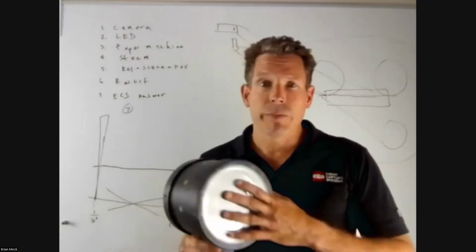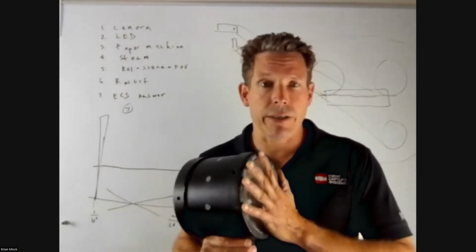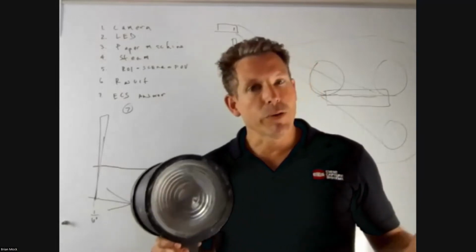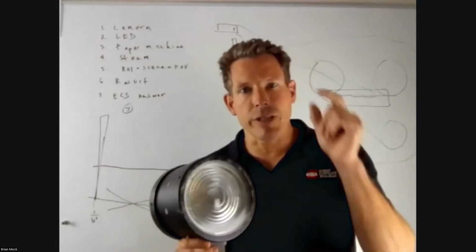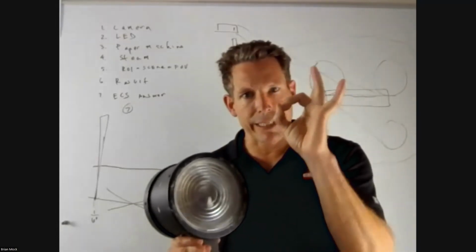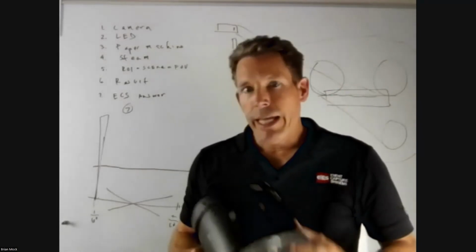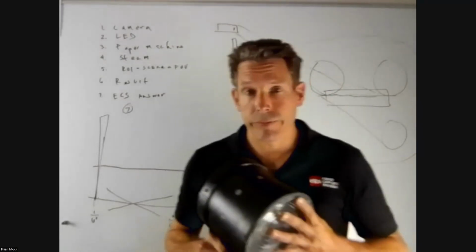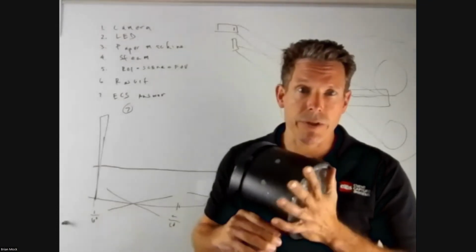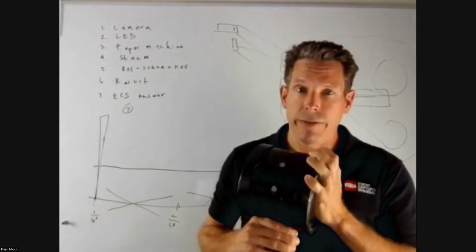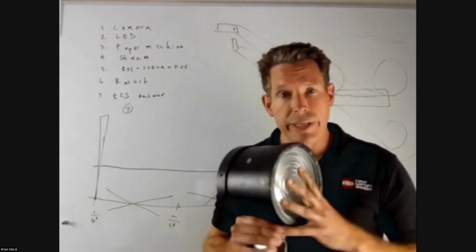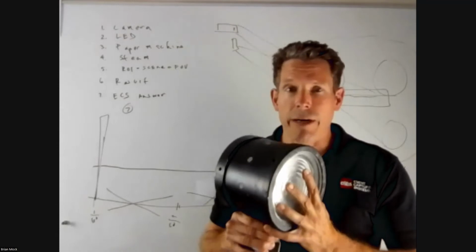And we're going to show some examples of what happens to the camera's ability to collect resolution when you don't use Fresnel lighting technology. In order to use Fresnels, though, you can't use individual LEDs all over a board like a pancake. You have to concentrate that energy as tightly as you can. And the fact that it has no electronics means that this light head can survive with no air inside your dryer section up to 220 degrees Fahrenheit. There's nothing to burn. The driver and the power supply are remotely located. So this can live in that environment without air.